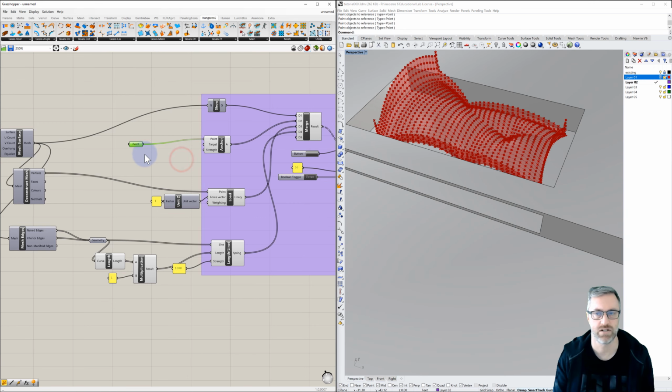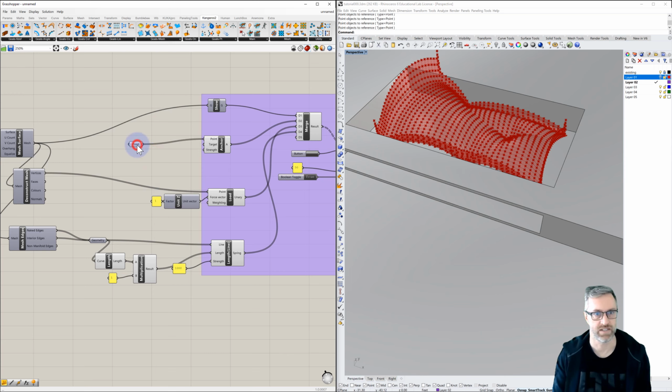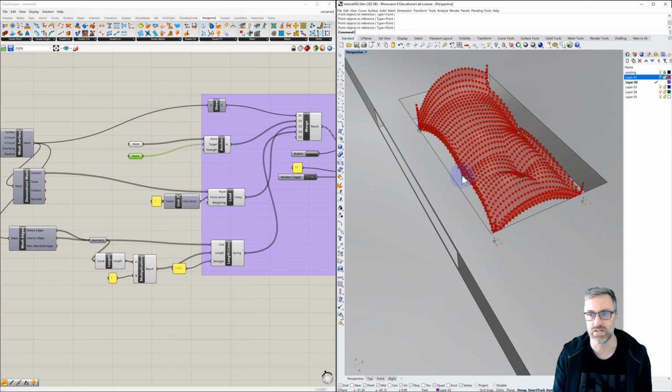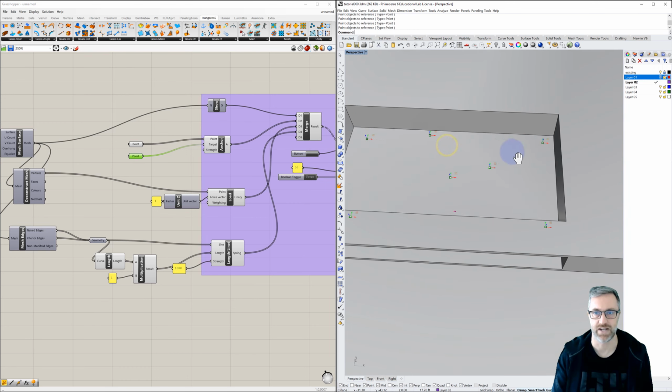What we can also do is, let's click on our point, and we should internalize the data. And then I'm going to copy those same points and set them as a target. Now we can see as I highlight the target points, this will allow us to interactively manipulate them. And so as I select a point, I can pull it up. And so what these are, the anchor points are the starting condition. The target points allow us to set a final condition.